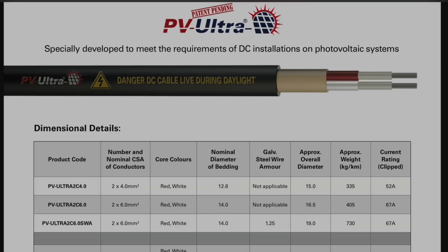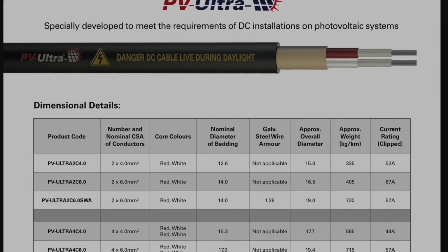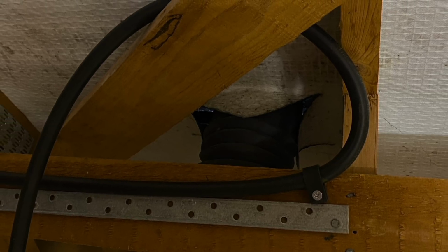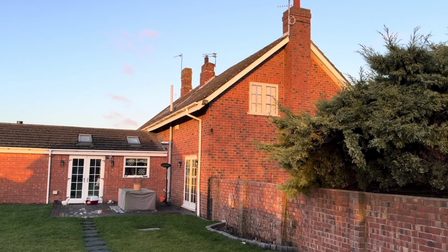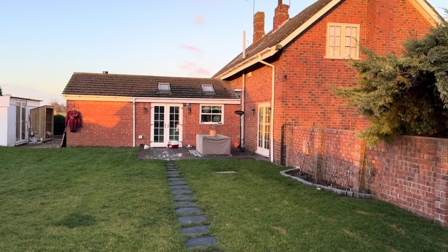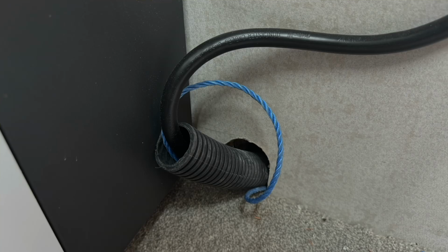Doncaster Cables have produced the PV Ultra, which combines all 4 conductors into one cable and can be easily clipped to a surface direct to the inverter. If you have to install cables overhead, then a suitable catenary wire, suitably supported and rated to take the weight, is required. Our installation will be installed in ducting to go out to the garage.